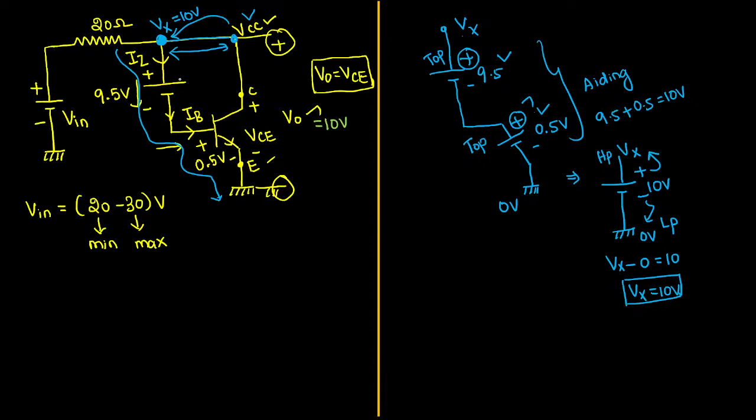Next, they told us that we have to identify the maximum current consumed by the Zener diode. Sir, how should I do that? Now you have to think. First, we already made one conclusion. I told you that the Zener current and the base current are both the same because both are connected in series. Sir, then where is that RB? RB is there, but RB is useless. Why? They have told us that no current flows through RB. So you can neglect it. So the Zener current and the base current are both the same.